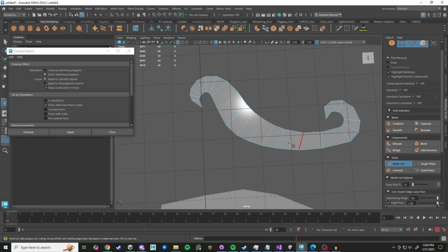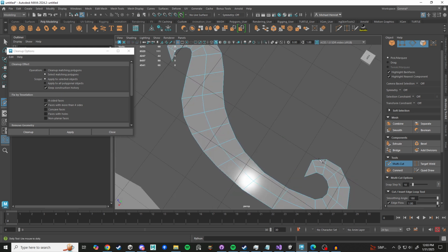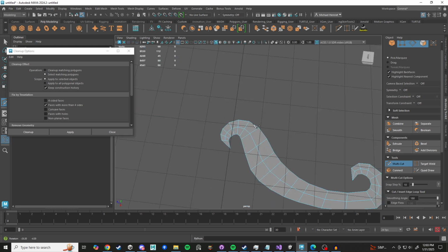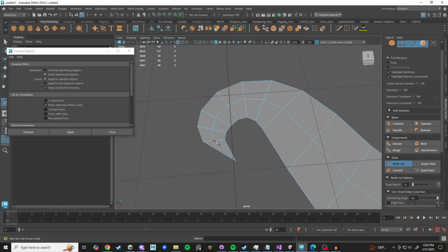And then if we wanted to give this some three-dimensionality, we can go for that, and I'm just gonna do Control and middle click, and that's gonna blast through all of those faces. Let's continue this cut. Oh, make sure you turn off edge flow, otherwise you might get some unexpected results there. And then here we go.